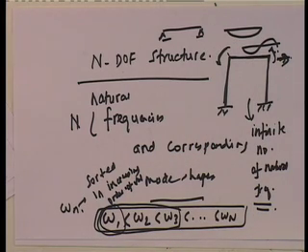So, I have completed my equations of motion, and I have introduced that ultimately the free vibration problem is nothing but an eigenvalue problem, and we also saw that since M and K are positive definite symmetric matrices, the eigenvalues are all positive and distinct.